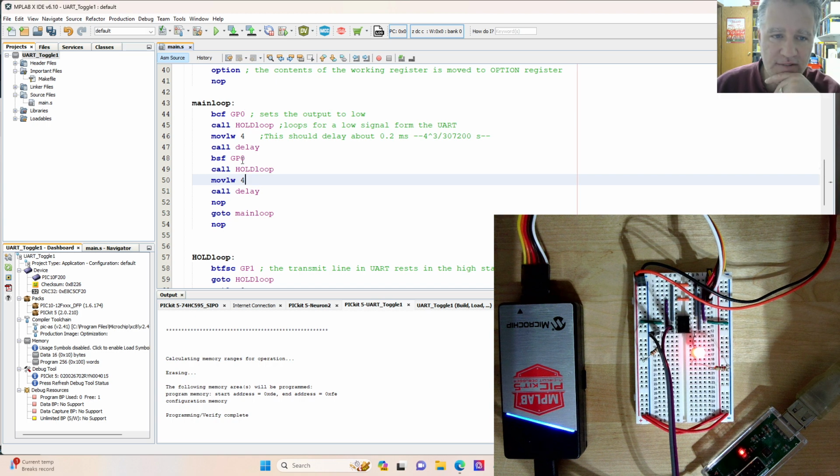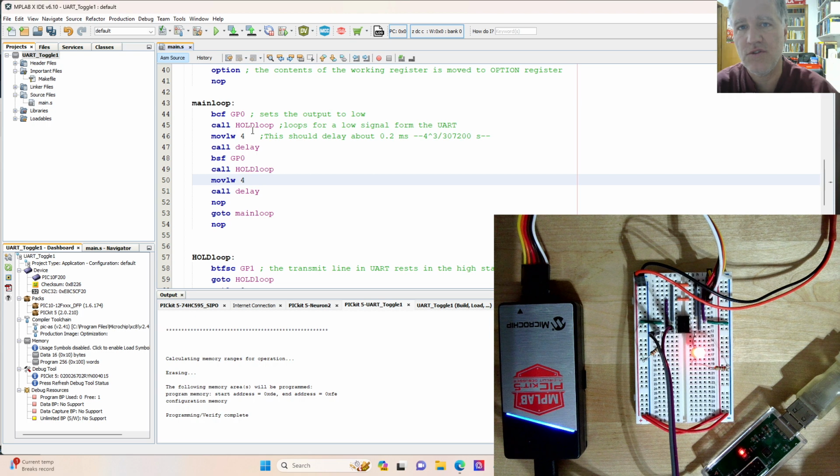And so essentially we have two regions here, and the hold loops are just spinning there until we get another signal. So it'll hold the system in a high state, hold the system in a low state. And we found this has worked really well. We've been using this in our setup in the lab for 6 months, and have never had any issues with the toggle switch working. We did have one of the PIC10F200s fry for some reason.